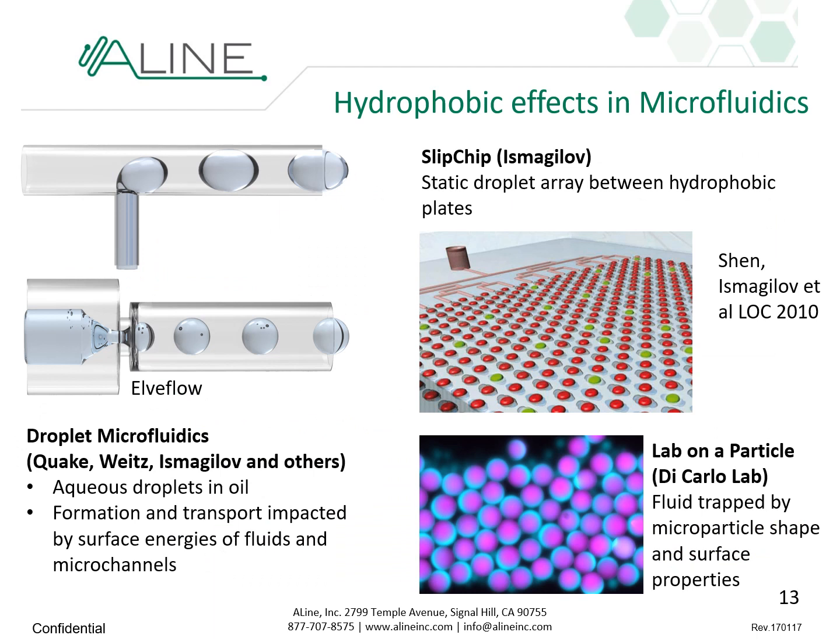Other effects are more on the hydrophobic side. You're probably familiar with droplet microfluidics, where you have aqueous droplets in oil, and the formation and transport are heavily impacted by the surface energy of fluids and microchannels. If you don't have the right combination of surface energies, by coating of the surface or surfactants, you end up with droplets that don't form with the right size, or droplets that actually get stuck and drag onto the corners, or wetting in the channels, and a mixture between droplets, which is something that is rarely shown in papers, but is actually a big problem for whoever has worked in microfluidics, and especially in droplet microfluidics.